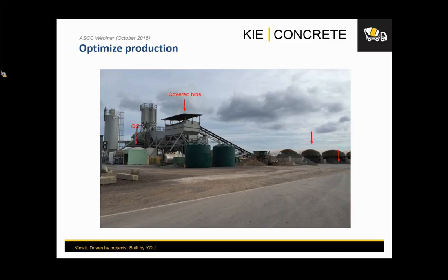You see those cover beams, and I bet you there's a very limited number of people that have seen that in actual production in commercial batch plants, right? That's very uncommon to see, and the reason why we did that is because in this location we have a lot of rain. Every afternoon we get rain from the condensation of the environment, and water comes down around 2 or 3 almost every day. So we wanted to maintain consistency in our production, so covering the bins provides us better ways to control the moisture in the aggregates that we're using for production of concrete.